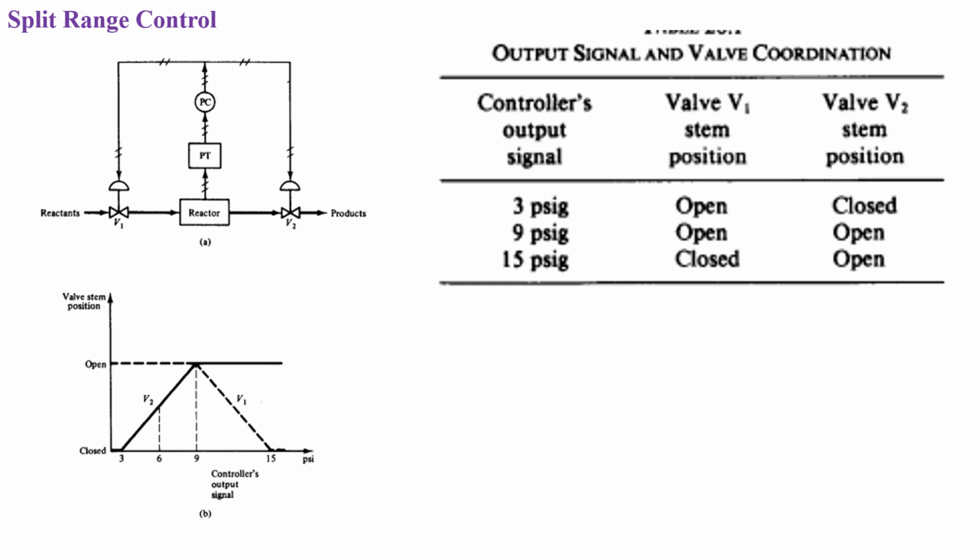Okay, but there is a rule: first concentrate on the secondary loop. We always know that proportional is simple and faster, so it responds quickly. So choose a proportional controller for the secondary loop, so that if it introduces any offset, that offset is taken care of by the primary controller. So always for the secondary loop, use a P controller so that it is faster. Even if you find any problem or offset in the secondary controller, it is taken care of by the primary controller. So this is how the rule is.